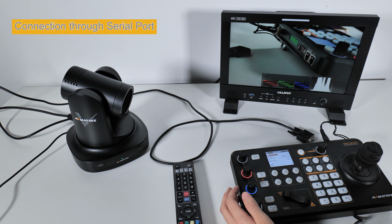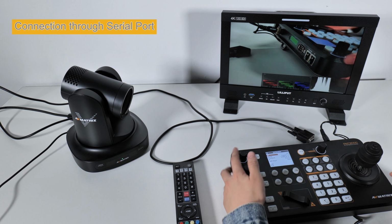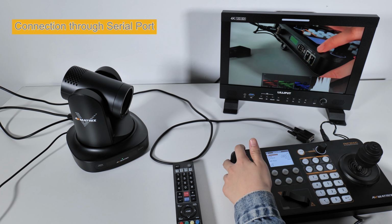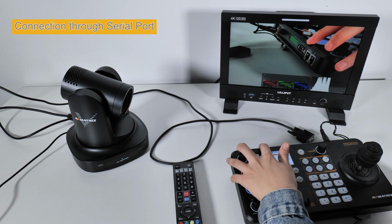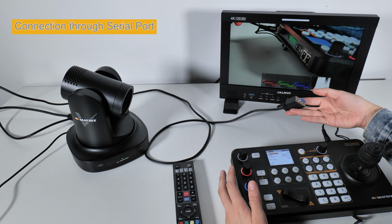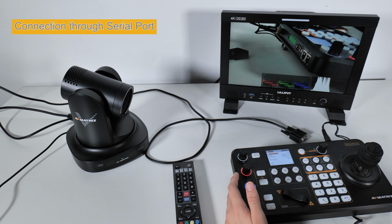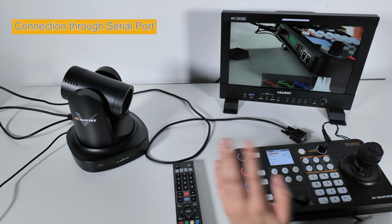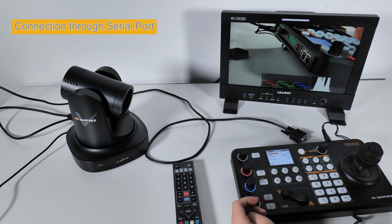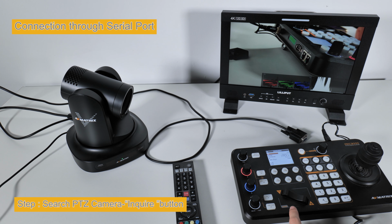The second connection type is connection through serial port, such as RS422, RS485, and RS232. This is the RS422 and 485 port. And this is the RS232 port. I will use the RS232 port to show you how to connect the PTZ camera and PTZ controller through the serial port. When they are controlled by the serial port, the PKC3000 can only support the Pelco D protocol, Pelco P protocol, and VISCA protocol.